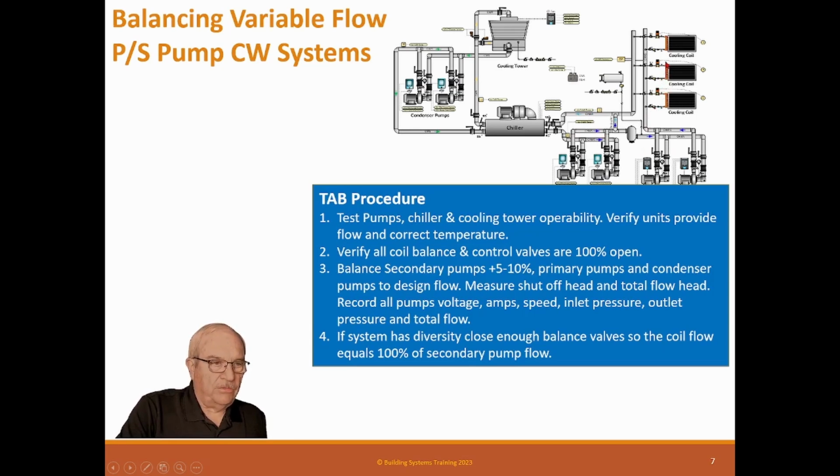If you close one, your GPM is going to be 480, and if you don't close the other, it's going to be 520. Pick the 480. You want just a few less GPM, so as you balance back and run up the head pressure, you still have enough water. Now, you can't do too much or else it defeats the way you're supposed to balance. But trying to balance with not enough water is somewhat complicated.